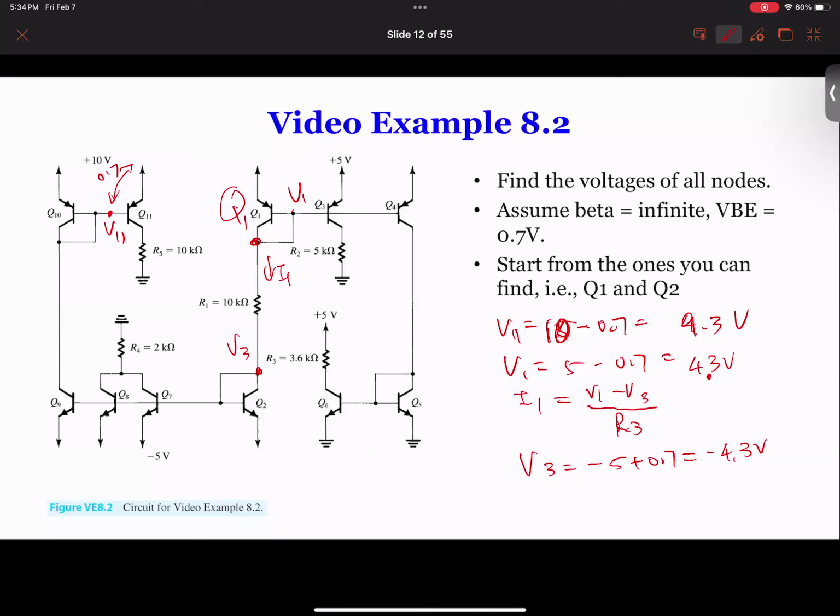So you can find the voltage over here, since this is ground. Current multiplied by 5 gives you the voltage over here. So we find that. And for this one, it's the same current. Basically, there's nothing to find because now we have the current and this 0.7 volts. Nothing fancy. And then we come to here. This is the current we know. Now we know this current is the same as this current, so we have 0 plus the voltage drop on here. So it's very straightforward once you find current I1.